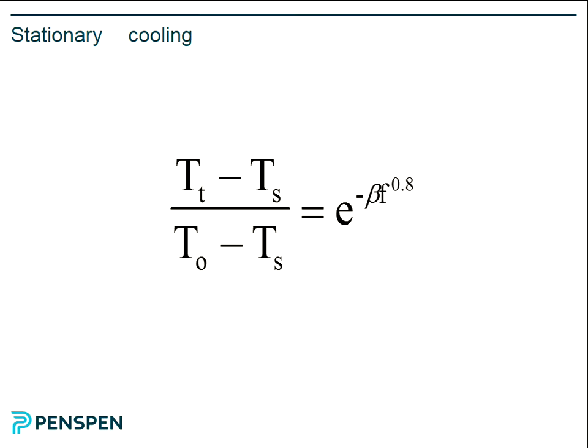And this is after 5 days. So you shut it down and wait 5 days. This is using a finite element analysis. You'll see now that the red is 17 degrees. So I happen to know, because I worked on this project, that the hydrate formation temperature is 16 degrees.